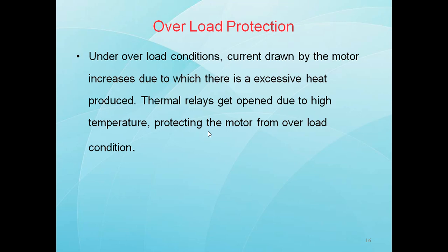Generally when current is more, more heat is produced. Then the thermal relay gets opened due to high temperature, protecting the motor from the overload condition. Like this, the overload relay operates.